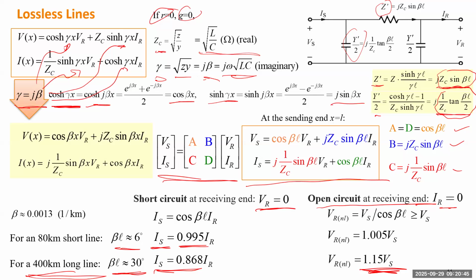So that can trigger some over voltage protection, because usually we expect the transmission line to operate within roughly 5% deviation. So if you operate 500 kV lines, you want to maintain the voltage everywhere within the range of 475 to 525, roughly 5% deviation. But 15% is too high and will trigger some protection. So that's just a quick run through of what we learned from last week.